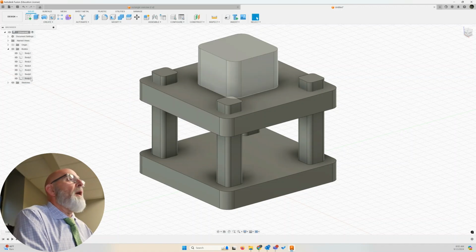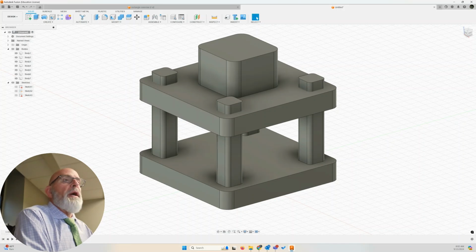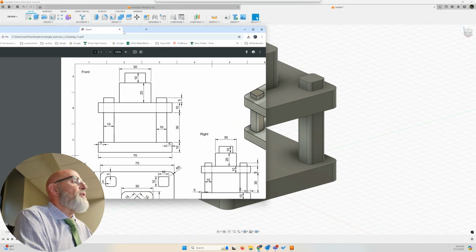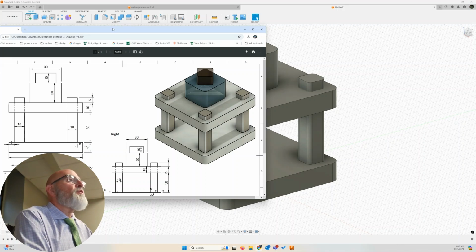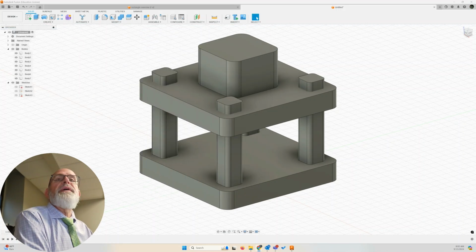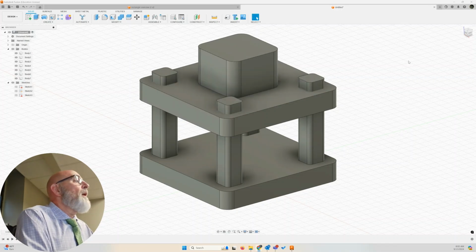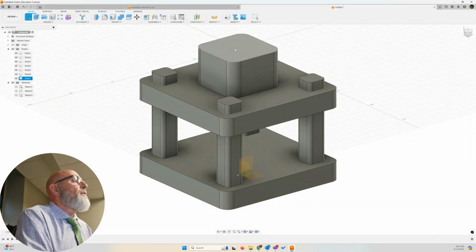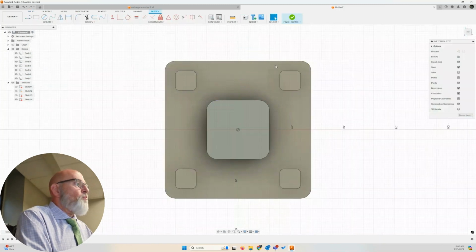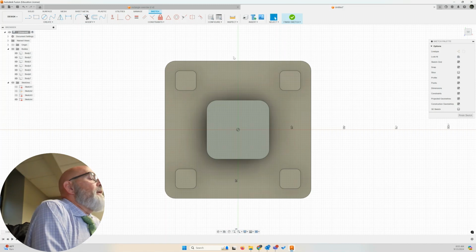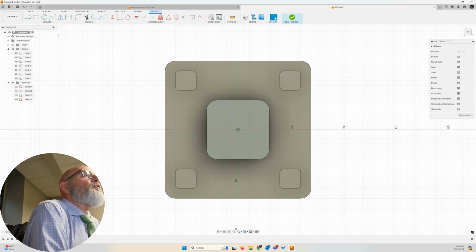All right, so I've got a new body in my bodies. There's my sketches. All right. Because in my diagram here, on my dimension sheet, that body has a transparent look to it. So, all right, let's draw the last rectangular shape up here on the top. So let's go create sketch. This very top surface. All right, let's do this to start off with. Let's go create line.